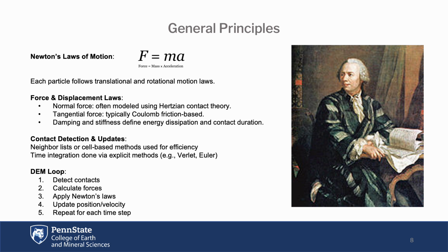For normal forces, it often applies Hertzian contact theory, which describes how elastic repulsion arises when particles overlap. Tangential forces are typically modeled using Coulomb's friction law. Damping and stiffness terms are included to realistically account for energy dissipation and contact duration.